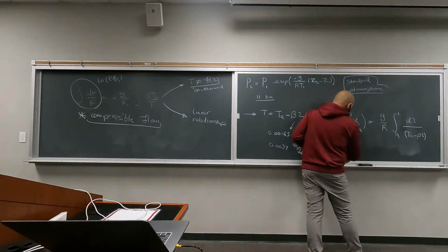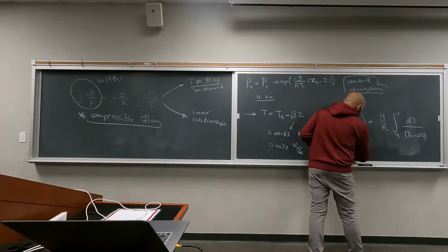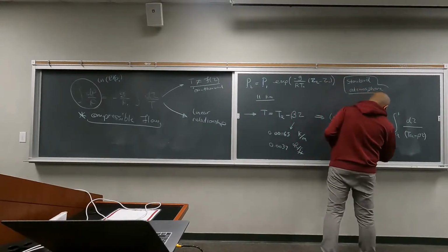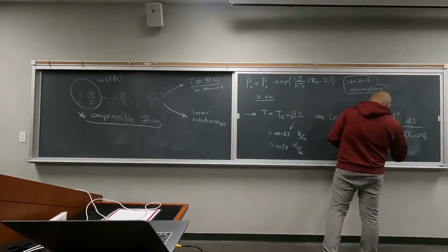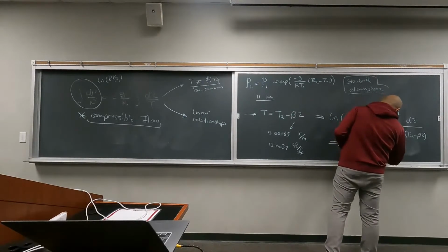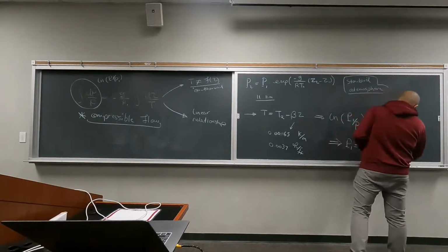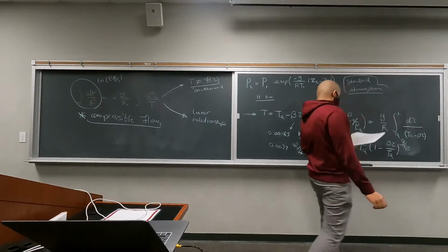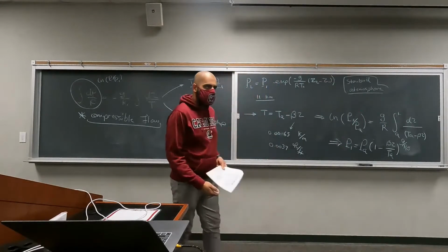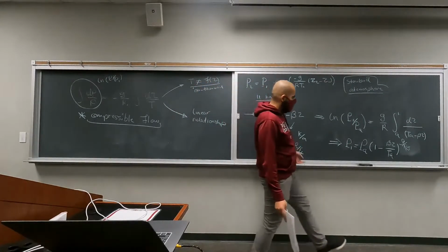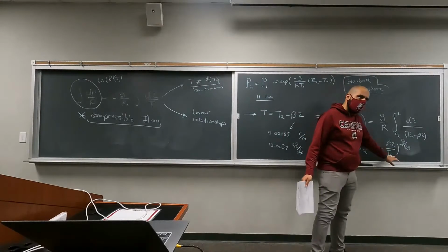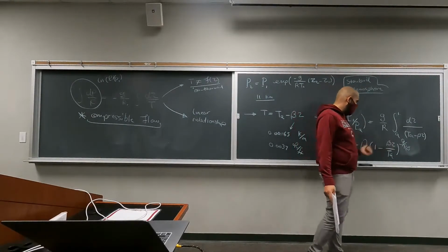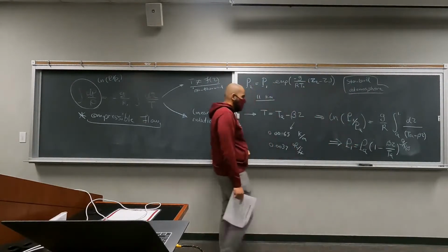So your P at point 1 is going to be equal to, if you take this integral, this is what you're going to get: PA multiplied by 1 minus beta Z over Ta to the power G over R beta. So as long as you have the temperature at the surface of the Earth, you have the pressure at the surface of the Earth, you should be able to calculate pressure at an altitude.